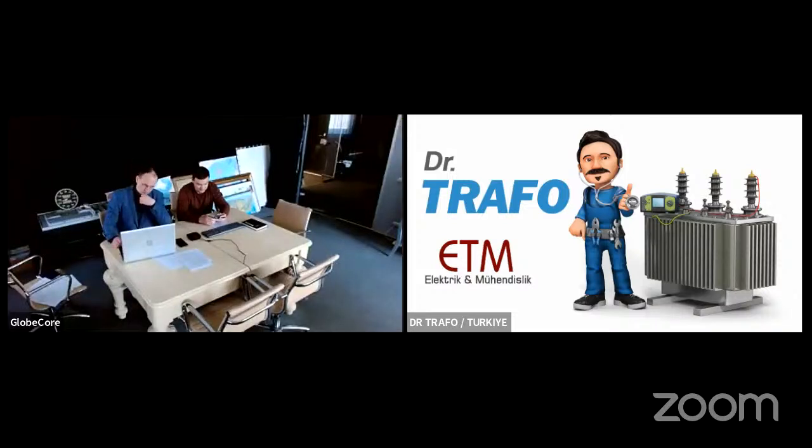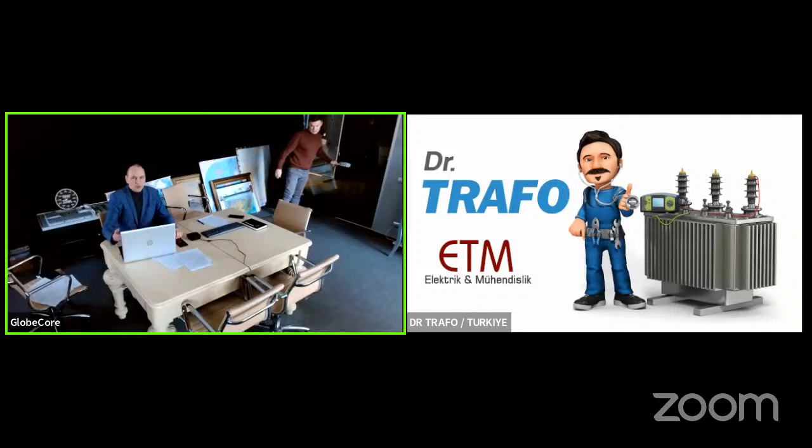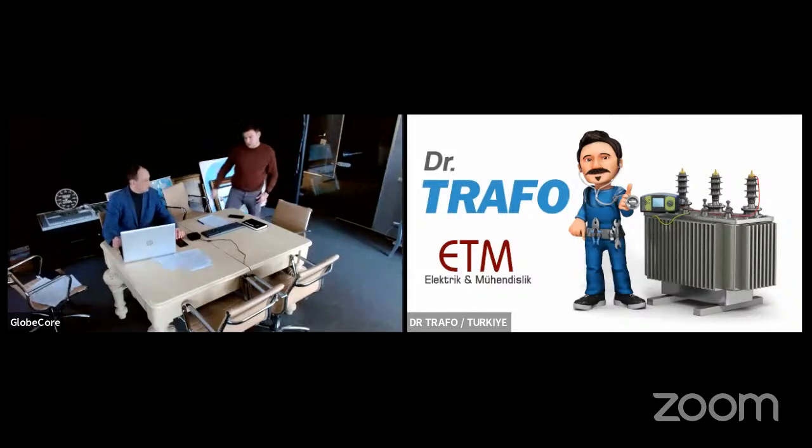Yes, breakdown voltage. Okay. As far as I remember, as per standard, the oil should be at a certain temperature before testing, because we know that with different temperatures of the oil, the water activity of the oil is different, and the specifications of the oil may also be different. So that is why our system demands to input the ambient temperature to get proper testing results. Is it the ambient temperature or the oil temperature?